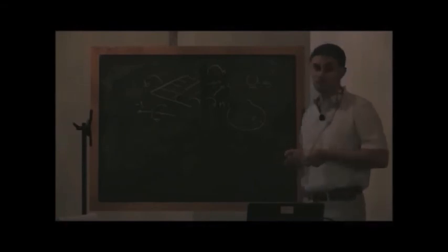Now the effect of the torque, the torsion moment, is that you put both beams into torsion. It is very close to the intuition of what torsion is in this situation. If you put the plate into torsion, you generate torques inside the beams. So it's a good illustration of what torsion is in plates. All right? So this is for the bending, the leading order, the thin plate model. And now what occurs if I look at the effect of the bending gradient?